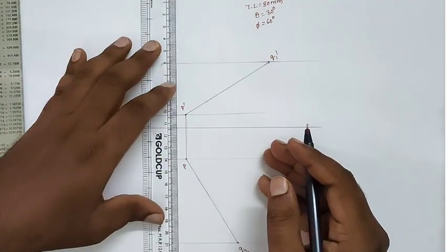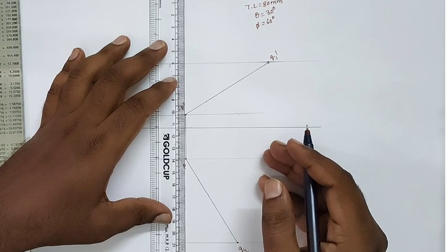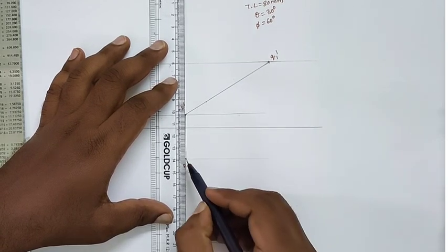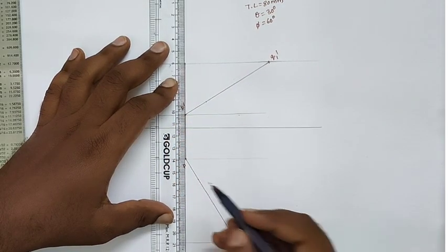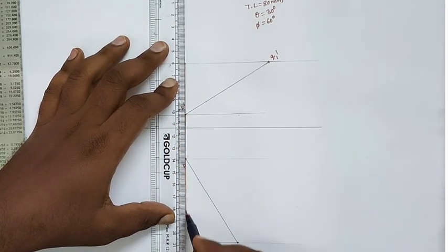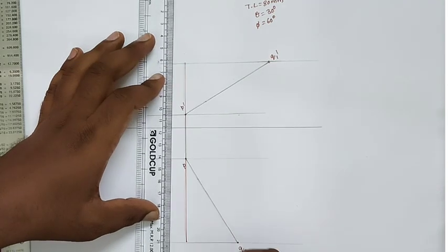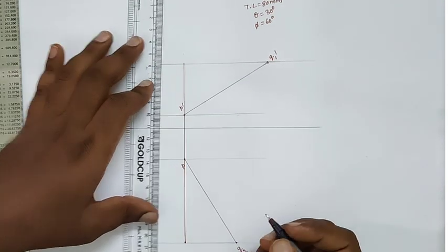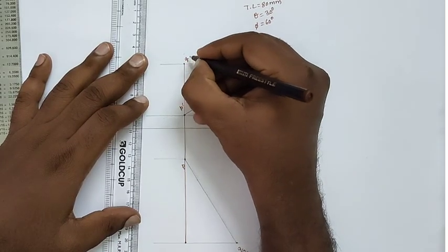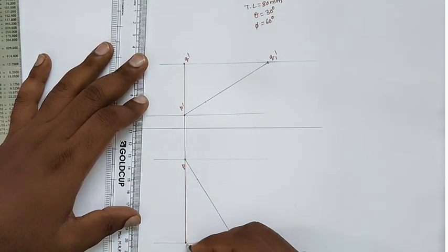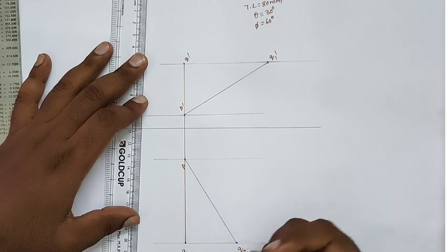So the projections are on the same projector line, so we can extend the P dash projector like that up to the Q1 dash horizontal line, and also the P projector in the downward direction up to the Q2 horizontal line, and here we will get the points. So they take this point as Q dash. This is our front view and this is our top view.